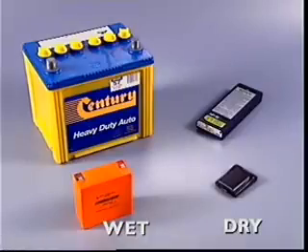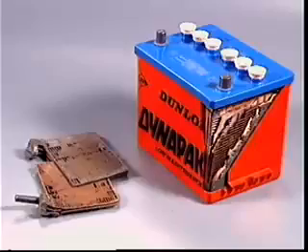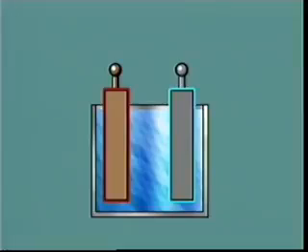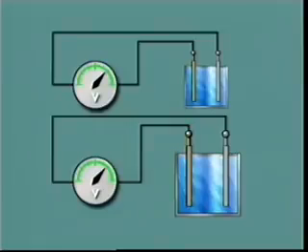There are two types of secondary cell, wet and dry. In automotive use, the usual main storage device is the wet cell of a lead-acid battery. It has two plates of dissimilar materials immersed in an electrolyte, a solution that conducts electricity by using ions. The accepted or nominal voltage of a cell does not depend on the size of the cell.